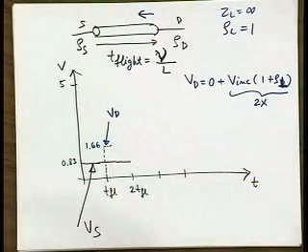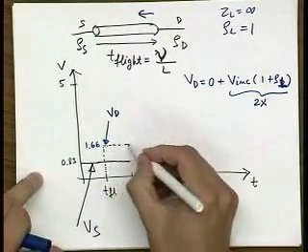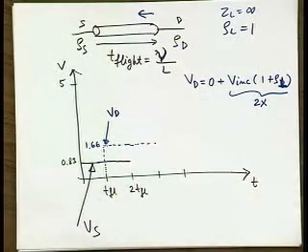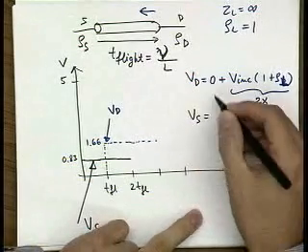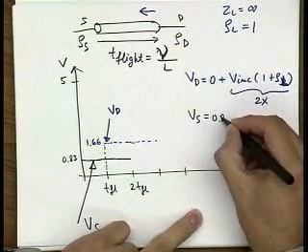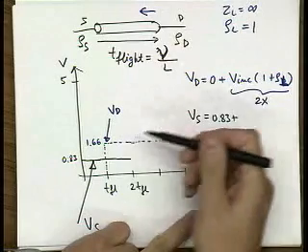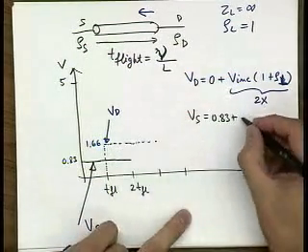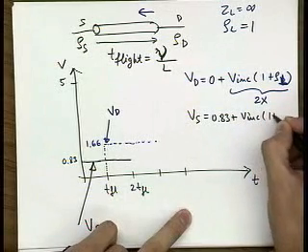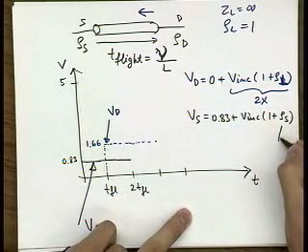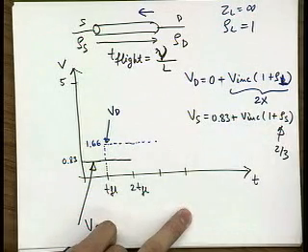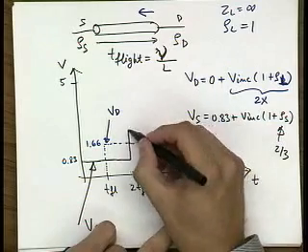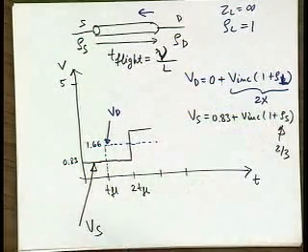Now once this reaches back to the source, at the source we will have Vs equal to the previous value of 0.83 plus this incident waveform that's coming back, 1 plus this, which is the 2/3 reflection coefficient at the source side. And then you have your signal going like that, and so on.